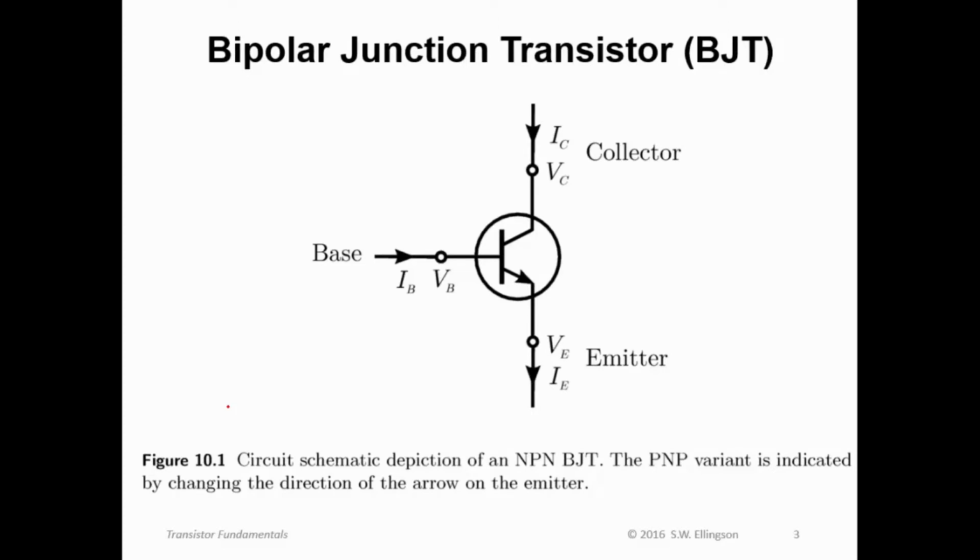Here is the bipolar junction transistor. This is a schematic element that I'm sure you've seen before. We indicate the transistor using this symbol. The arrow pointing in this direction outward indicates that this is an NPN, referring to the arrangement of the semiconductor materials within the structure. Also has some effect on the way it behaves. There are also PNP BJTs. Everything is pretty much the same with just a few very minor changes. So we're going to talk about NPNs here. The differences with PNPs is very, very minor.